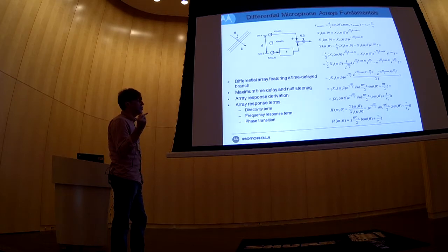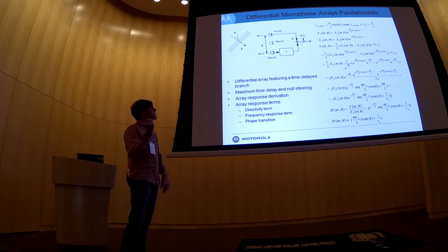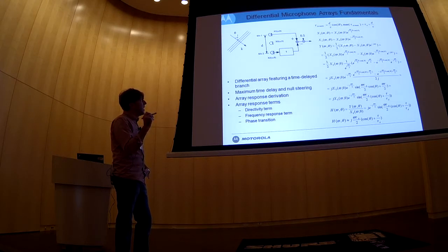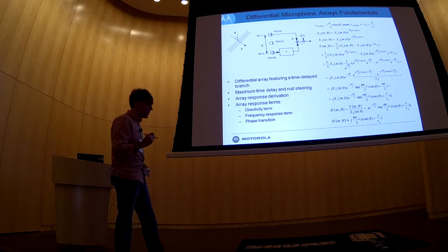Okay. So now the next thing that we notice is we define this term which is located at the exact geometric center of the array, and we call that a phase center. We only use that in order to define and calculate what the signal output would be out of microphone 1, which is this, and out of microphone 2. All that this says is that the signals out of microphone 1 and 2, if we had a sound source located like this, will be delayed or advanced with respect to the phase center.